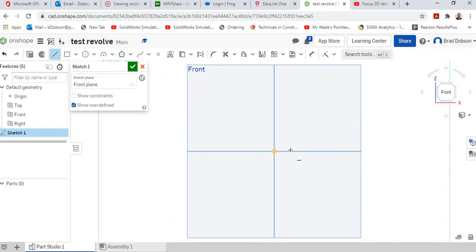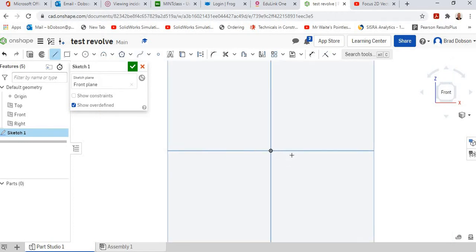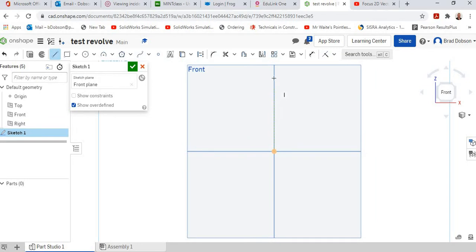Again, when you're doing revolve, one thing I've learned is you want to be somewhere near the right dimensions, because otherwise when you start dimensioning it, your original drawing can go a little bit off. So we're imagining basically that work plane running vertically up is the centre of rotation. So I'm just going to start off by starting in the origin and then pulling out. So again, you can see somewhere near. So if your base is 20mm, get somewhere near the right measurements. But I'll just run this through.